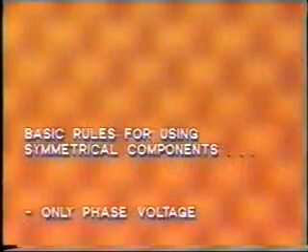When faults do occur, the power system no longer operates with beautiful sine waves and balanced phasors. At any instant in time, we may have voltages and currents going in several directions, with magnitudes and phase angles being imposed upon each other. Breaking the quantities down into symmetrical components helps us visualize the conditions. In fact, any unbalanced system of currents and voltage can be represented by a combination of positive, negative, and zero sequence components. There are several basic rules we should remember in connection with this method.